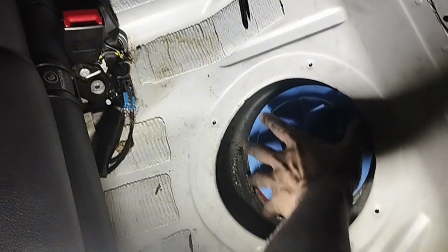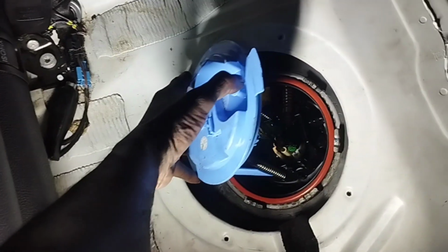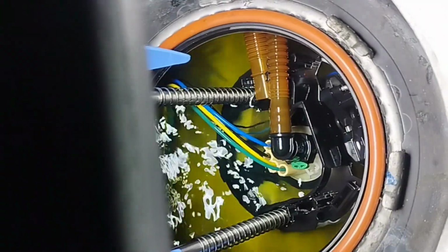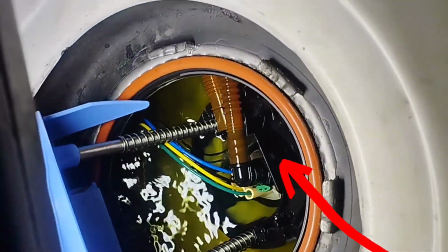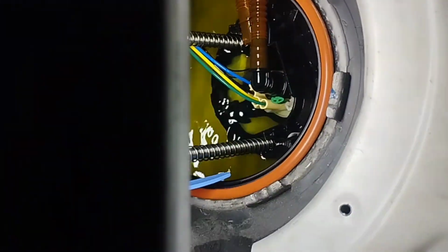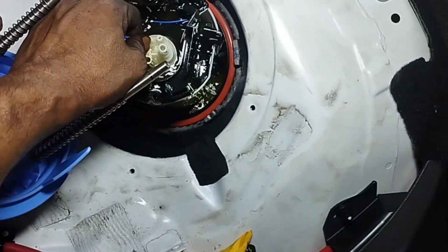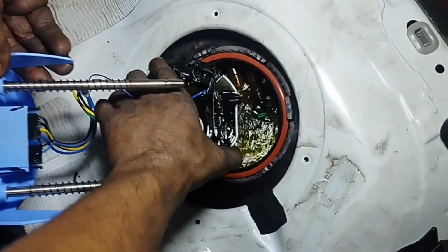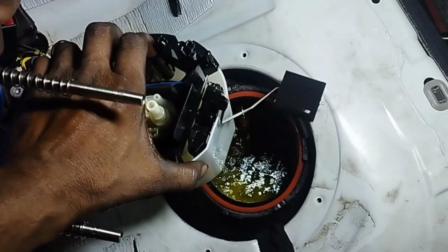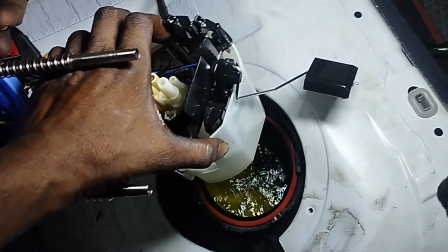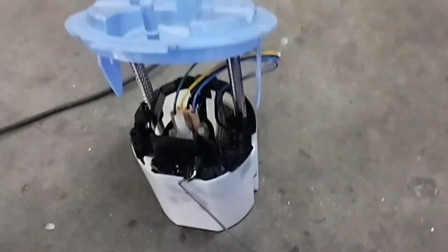After opening the top of the fuel pump and lifting it up, look inside and open the fuel hose pipe connection. To open the fuel pump pipe, press and hold this green lock inward and pull the pipe upward. Now I will take out the fuel pump. After taking it out, I poured the petrol inside the fuel pump again into the fuel tank. The fuel pump is not working, so I will change it.